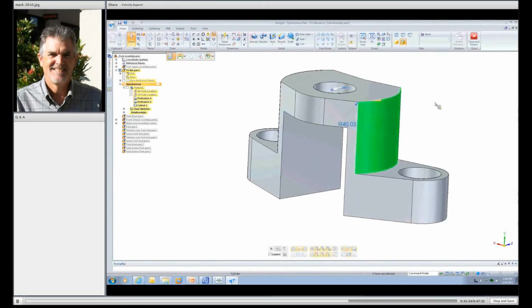Now you'll notice where the steering wheel is. I'm going to click on that steering wheel and move it, and you'll notice when you click the center point, you can move it wherever you need to. In this case, I'm going to put it on this face here, and then I'm going to use the Shift key and rotate, and lock it in so I can rotate this face a little bit for us. And you'll notice here, as I move this face out, it's moving both sides because they're symmetric.